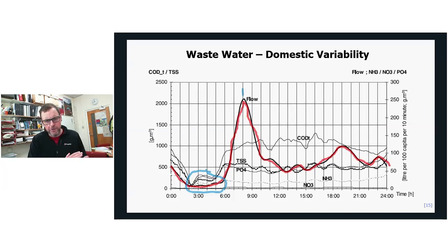By and large the first thing people do after they've checked their phone is go to the toilet, maybe have a shower, brush their teeth, and make themselves something to eat. All those things consume water and result in discharges to the wastewater system. So that's what you see here. Virtually everywhere I've ever seen, the peak in flow happens at that morning peak.